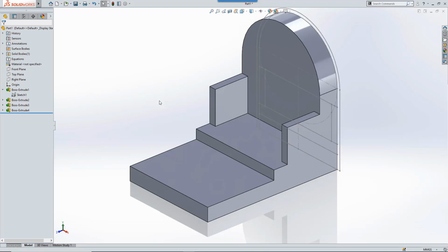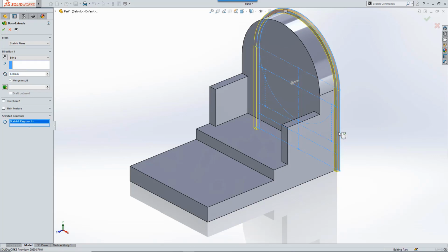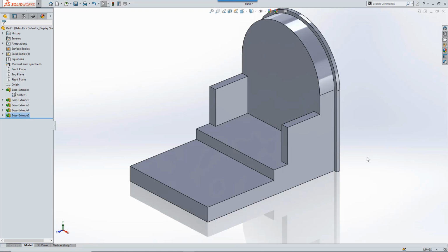There's one final extrude that I'd like to create, so I'm going to show the sketches again, and if I pre-select the sketch, because I've customized the shortcut menu at the start to include the extrude command, I can select it directly from here. We'll fill in 3mm, choose our contour and use right click for enter. Finally we'll use our mouse gestures to hide sketches.